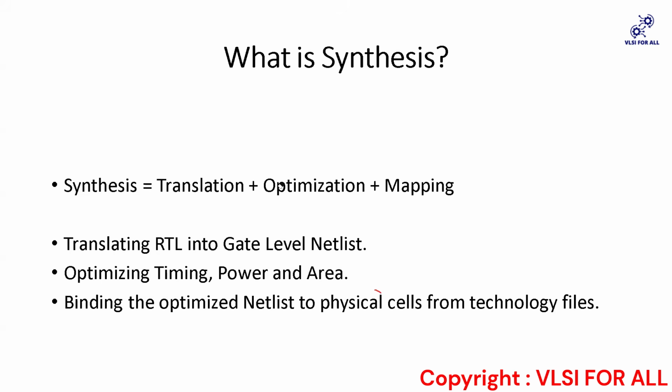Okay, do you know about scan buffer cells? Yeah, of course, you know scan insertion. Like for DFT also you do scan insertion. It's basically connecting the output of one flip-flop to its sequential flip-flops. So the output of one flip-flop will be given to the input of the other flip-flop, and it forms a chain. And we just need to compare whether the output which we are getting is the expected output or not.